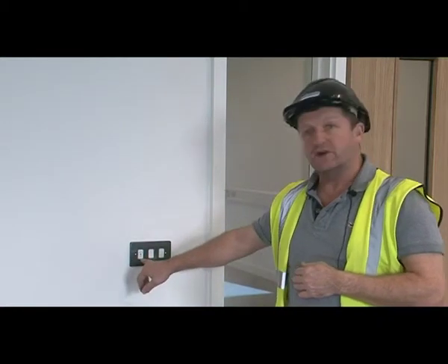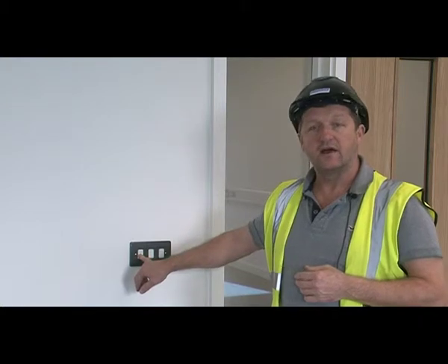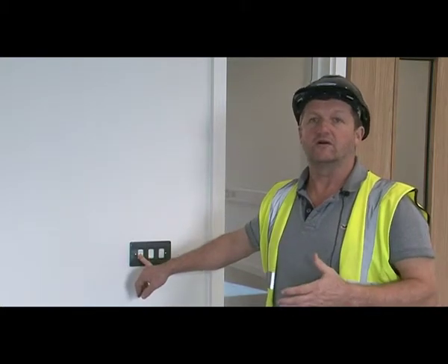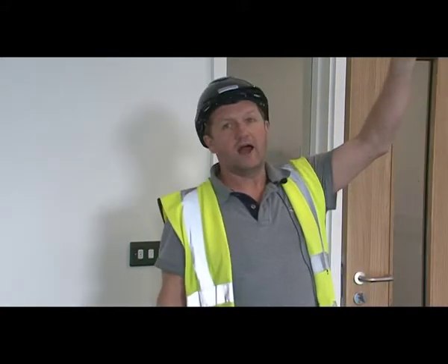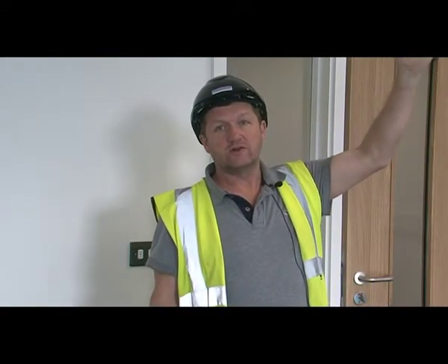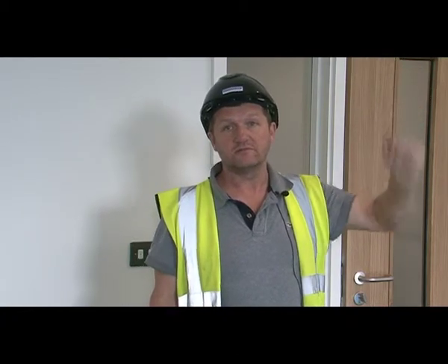The third switch is for the caretaker. That is a key switch, and there is one located in all classrooms which puts the emergency light at the door into emergency mode, and then you can leave that for its 3-hour duration test once every 3 months.